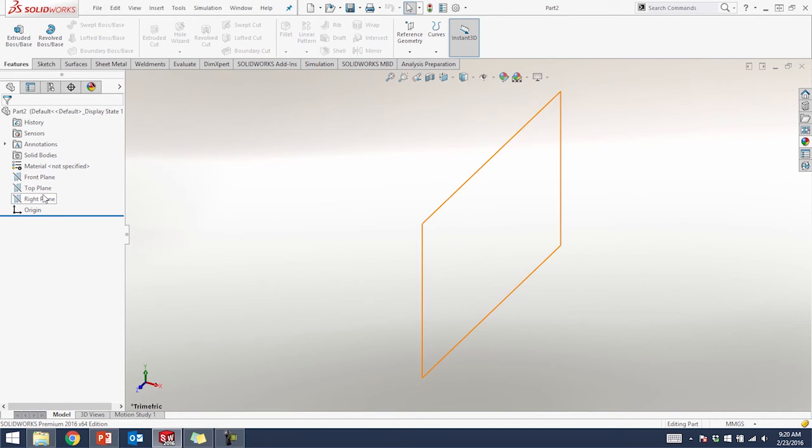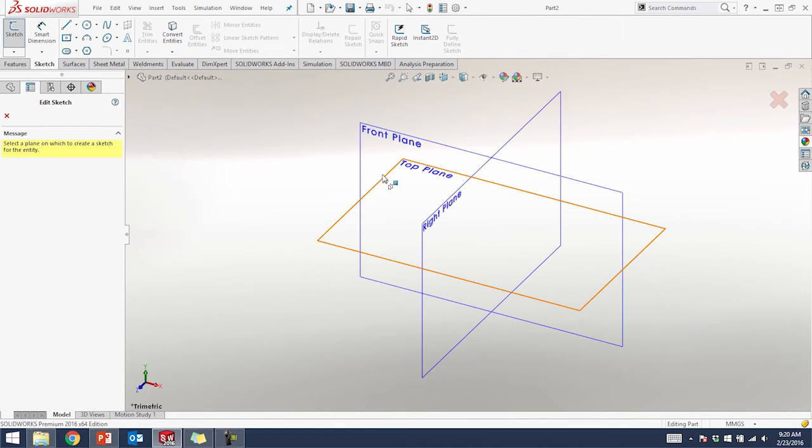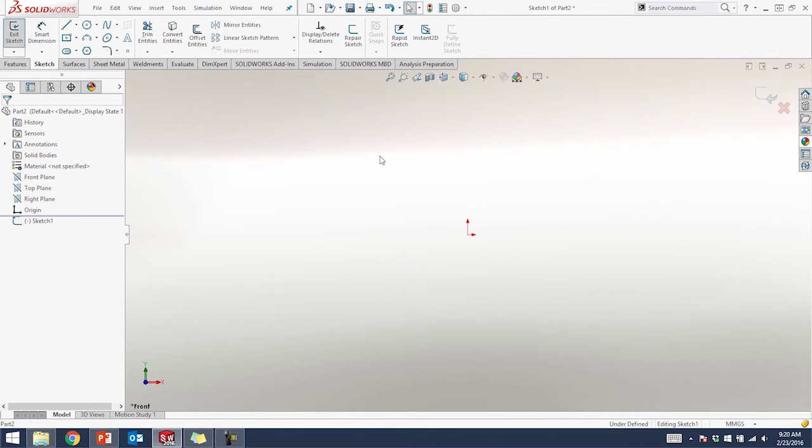So these are the planes I was talking about earlier, the pieces of paper I'm going to sketch on. If I want to sketch, where am I going to go? I'm going to look at the screen and find a tab that says Sketch, and then I'll probably press the button that says Sketch. Very intuitive. I like to start sketching on the front plane. Develop your own personal habits based off what's simplest and makes the most sense.